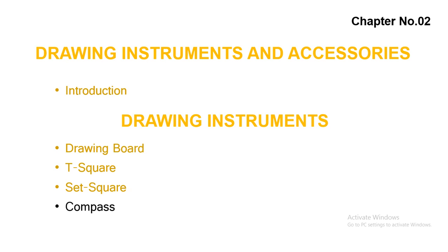The first type of compass is not considered good because it is difficult to set up. This type of compass connects both legs with a pin. If the joint is tight, it is difficult to set it up accurately for specific measurements. On the other hand, if the joint becomes loose, its legs open automatically while drawing the arc.